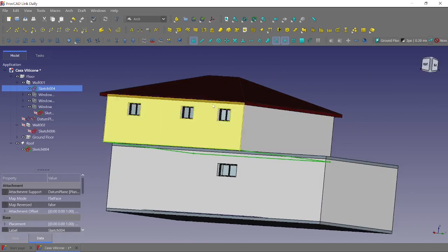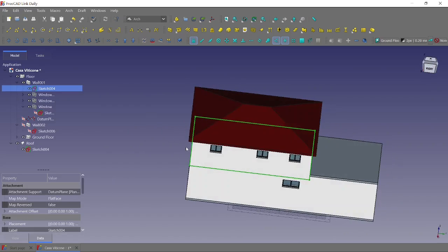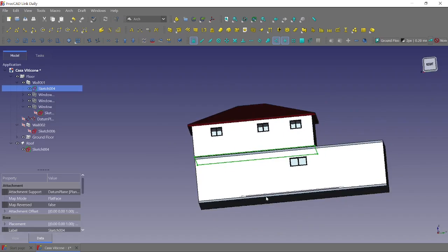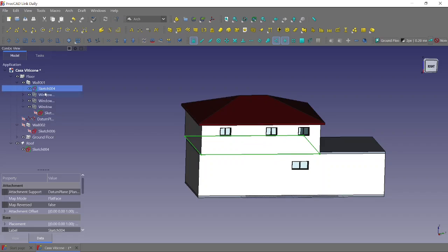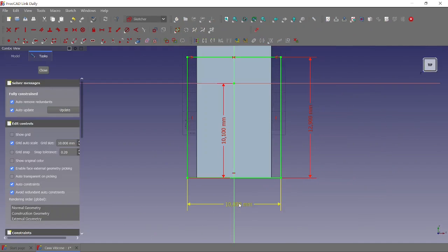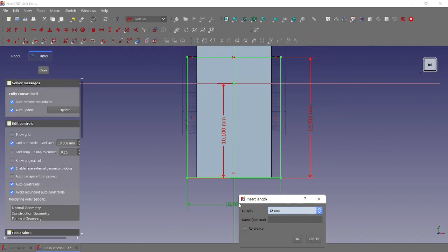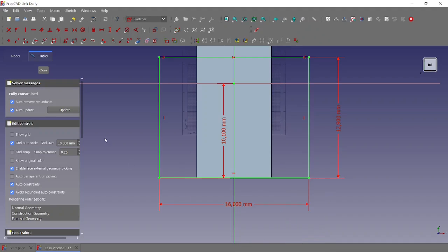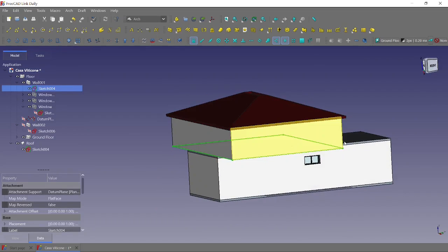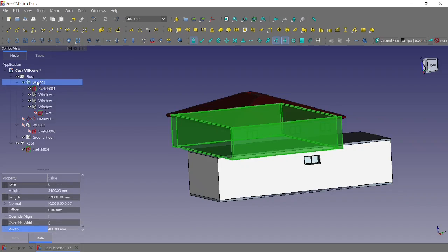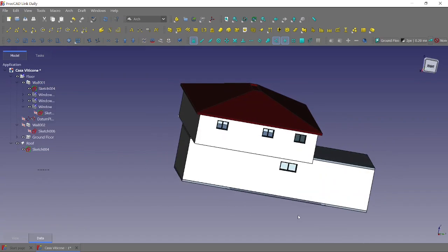See that? So now when I'm stretching, moving walls, my windows are adjusted accordingly. We'll just test it again. 12 meters. Let's go a big stretch. I'll just show you what happens. Close. So big stretch. Looks like everything's lost, but it's not. Just go up to walls, right click, recompute object, and you have it back.